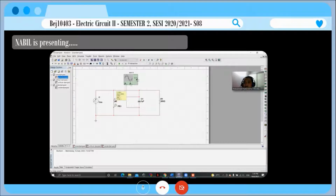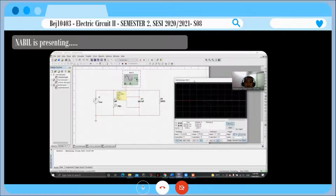For the overdamped, we use a step source, an inductor, a capacitor of 1 microfarad and a resistor of 500 ohms, and we connect to the oscilloscope at channel A. We run the simulation, and the overdamped graph is like this.